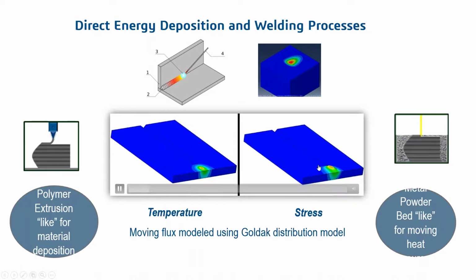These distortion results could, if required, be used to compensate the geometry, if the structure warps or deforms. In some cases, we want to compensate the geometry for that. So we could bring that back into the geometry more or less and rerun the simulation and validate how a pre-compensated geometry would conform to the nominal measurements.